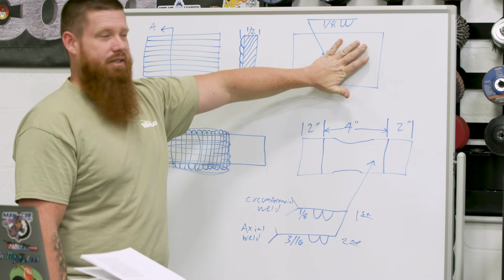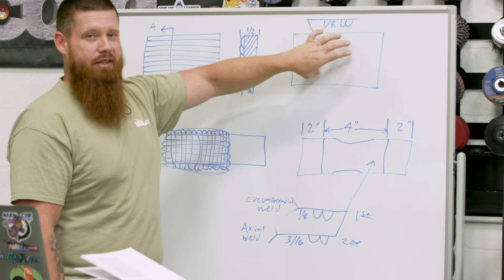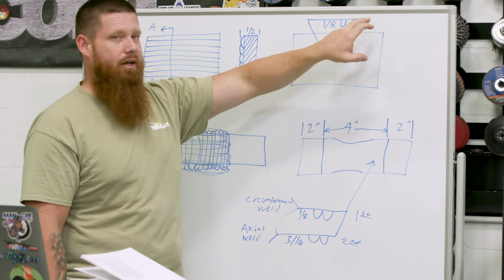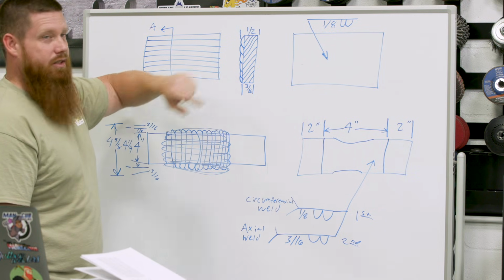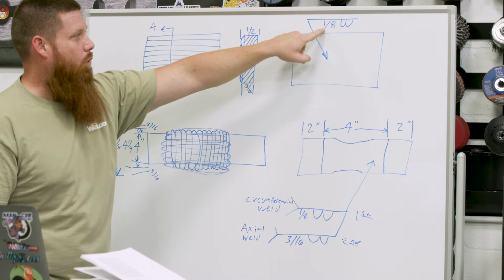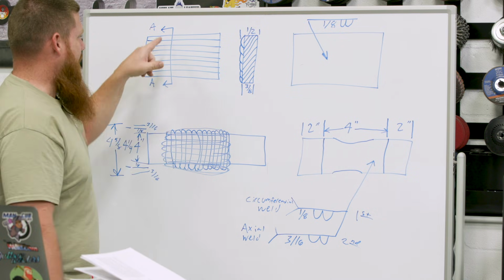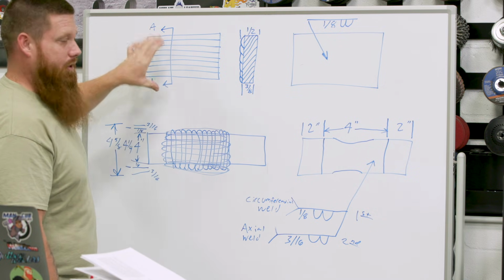I have just a regular piece of steel, and I'm going to do some hard facing on there. So they'll list the electrode out here, the welding process. We're going to take this 3/8 plate. Once we're done, it's going to be 1/2 inch thick because we put that 1/8 padding on top of that. And this is our section or cutting plane line.